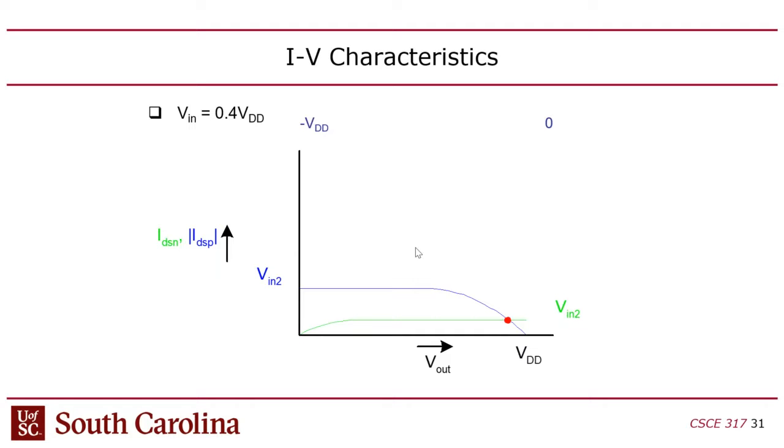And then 0.4 VDD, increase the voltage a little bit more, and so on. Now, at some point, sorry, let me go back here. At some point, once you hit 0.4 VDD, let's see, 0.4 times 1.8 volts. So you're getting close to the threshold now of the nMOS transistor, right? So the nMOS transistor is now transitioning out of cutoff at this point.